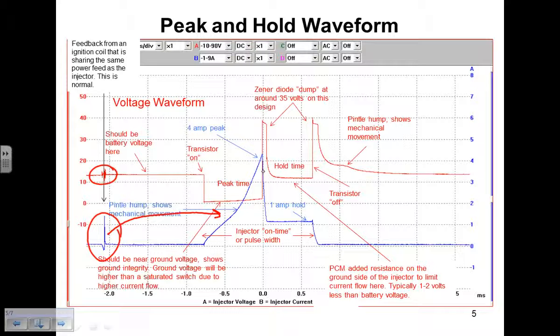You just need to understand that you have a voltage spike from that ignition coil that's being shared with that fuel injector. So you've got a coil firing in a different place for a different cylinder. At the same time, you have an injector firing for a different cylinder that isn't on its compression stroke yet. It's on its intake stroke, and they can end up being the same. So look for that. Be careful with those spikes.